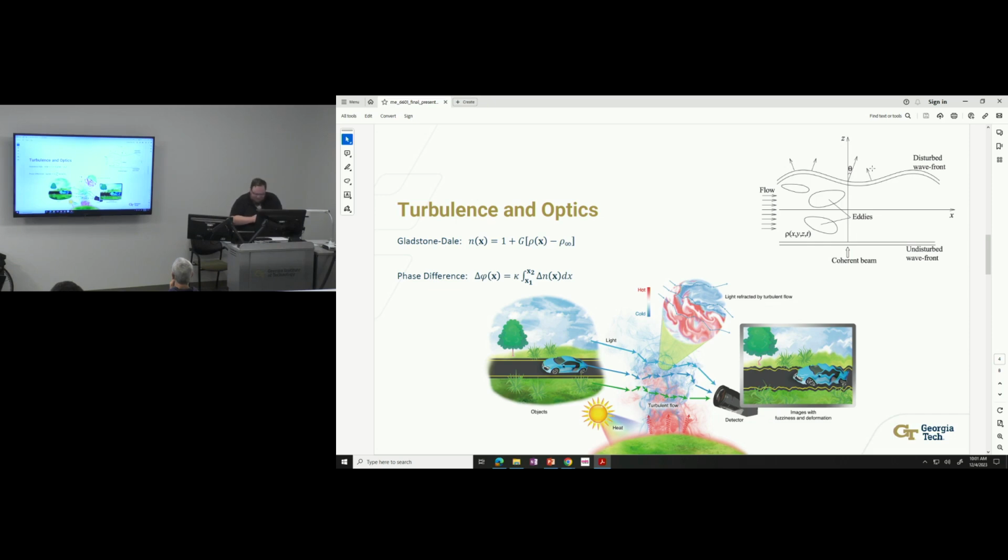So for camera imaging, the phase information isn't that important. But for coherent laser systems where data regarding target information or modulated communications is phase encoded, this makes it difficult to reconstruct at the receiver, assuming you can even measure the signal at the receiver in the first place. So turbulence isn't causing the energy in the light to get lost. It's stretching that energy along the axis of propagation of the beam so that there's much less energy you'll see at your detector per unit time.